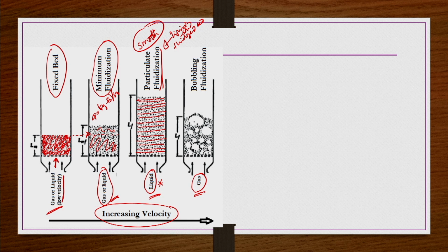But now, if you have a gas-solid fluidized bed, and the superficial velocity of the gas is sufficiently larger than the minimum fluidization velocity, we can have a bubbling fluidization bed. That means some voids or bubbles are forming here, like that I am arrowing like this, and these voids or bubbles are almost free of particles. Within these voids or bubbles, there are no particles in general, or very few particles. Such voids or bubbles are formed.